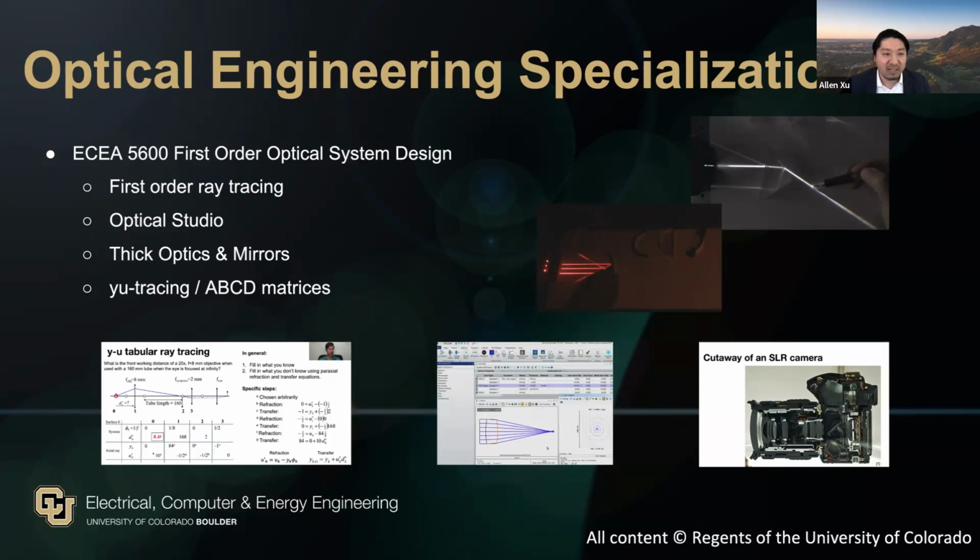We'll incorporate actual glass designs into Zemax Optical Studio, a software that will be available to you, which enables the simulation and understanding of complex optical systems like zoom lenses. We'll analyze spots formed on an imaging plane and optimize the configuration based on the desired application. The process of optical design starts with first-order principles, followed by basic calculation to define their desired functions, derivation of the lenses that achieve those functions, turn them into real optical systems, and again, optimizing performance using software like Optical